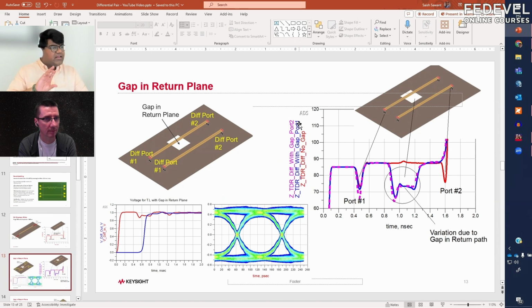Okay, and then I'm just switching the S parameter and now seeing it from port 2, and you see it exactly overlay. So you see that you are not seeing this port out here because of the resolution, and that's what I had shown you previously as well, that you need enough rise time and all of that.